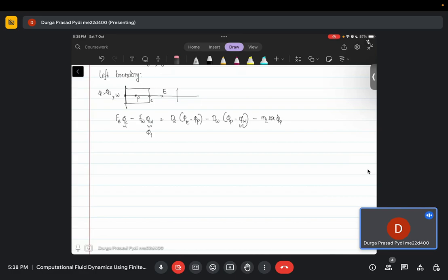So what we do here is we just take the half cell and write the gradient term there. So this term will essentially now become dW times phi p minus phi west boundary by, I am just writing a half here, so it will be 2 times dW.